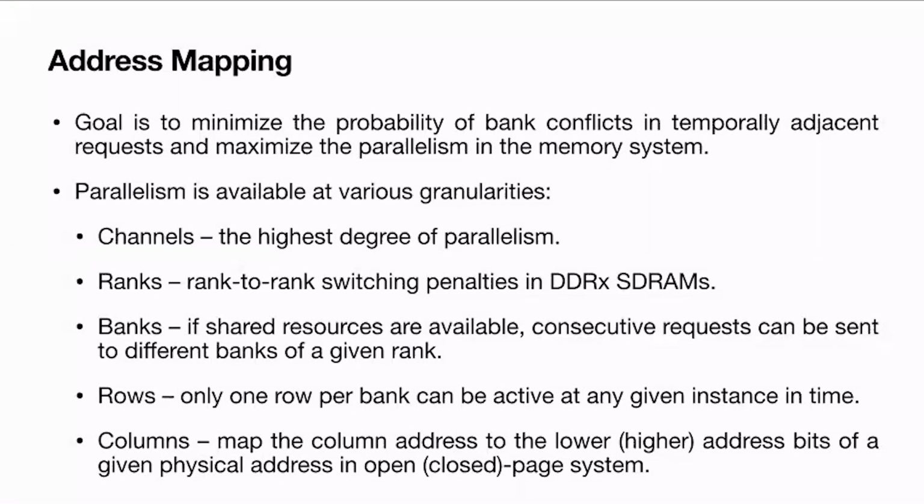And the ranks, it is better you put the data into the same rank rather than distributing across multiple ranks inside a DIMM, because rank to rank switching of 6 DRAM cycles is going to take place. So the rank to rank switching penalties will be there, and you need to try to minimize that.